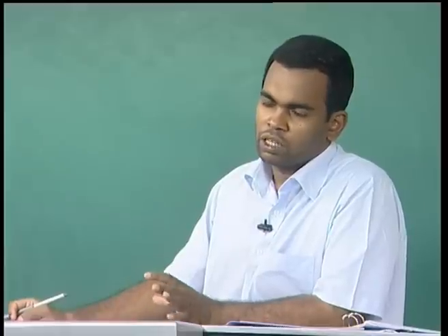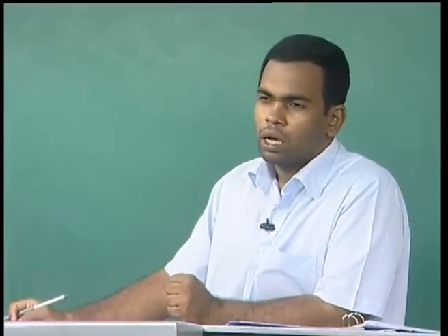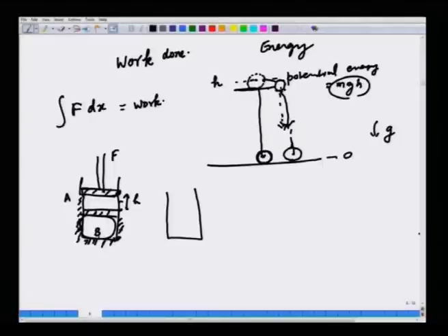Now, in the state B also, once you have done work and given some time for the gas to settle, the gas will be static. So, what has changed from state A to state B? What has changed is the internal energy of the system. This is a new concept, it is not there in mechanics, it is the concept that comes from thermodynamics. Internal energy of a gas or a fluid in general is that part of energy that is stored in the molecular degrees of freedom of the fluid.